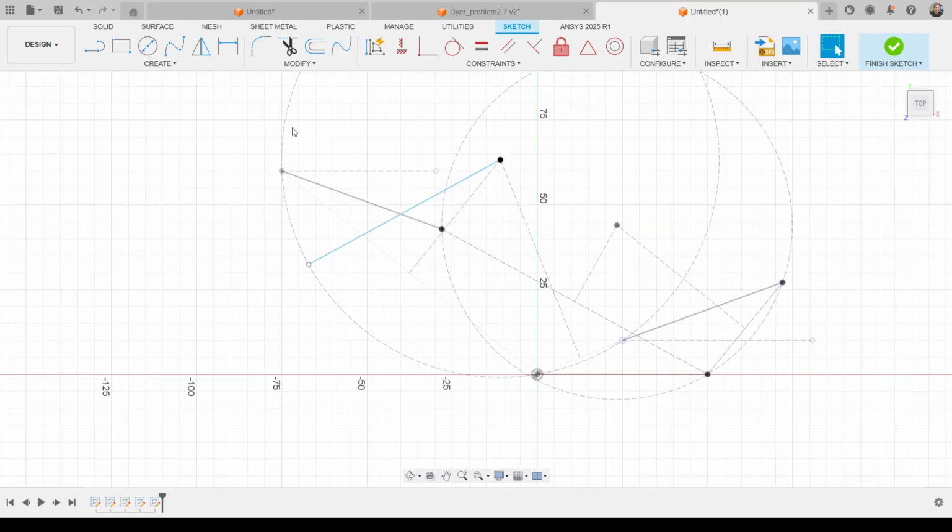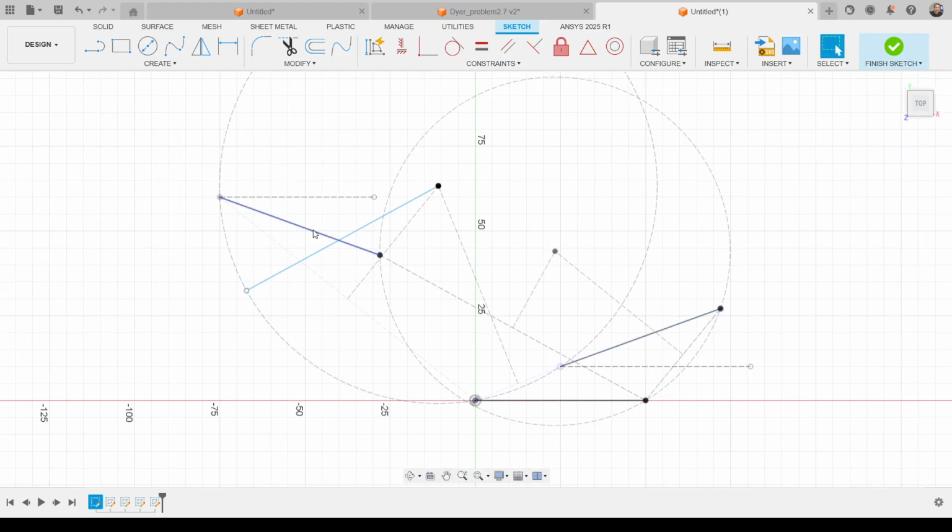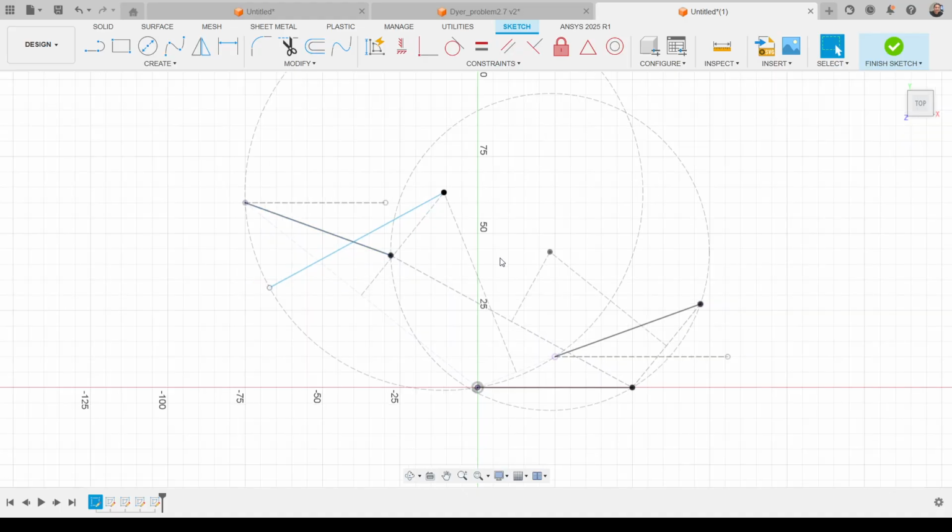And then we have this other circle, but it comes from another sketch. So I think that now we can turn on sketch 1 with the 3 different positions for our coupler, and now maybe these 2 circles, which are clearly defining the positions for the joints A and B, will be useful, but now I need a third circle.